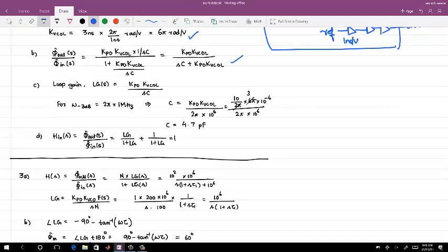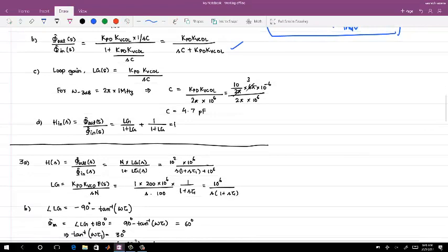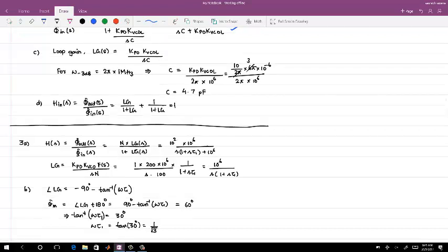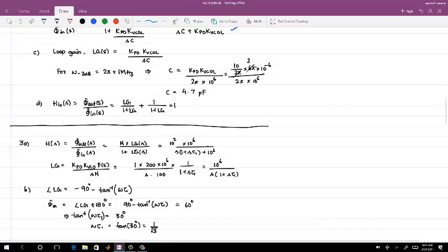Determine the value of the capacitor to achieve the jitter transfer function bandwidth of 1 megahertz. This is also a first single pole transfer function. In the case when everything is connected, reference and input are shorted, so you have the same frequency and your transfer function is 1. So the question would be, what's the benefit of doing that? You can get multiple phases for the delay cell, whatever you are having.